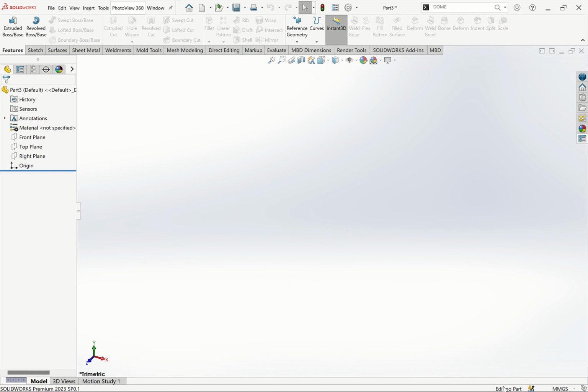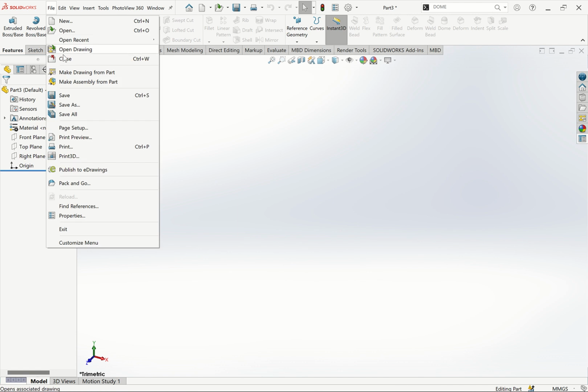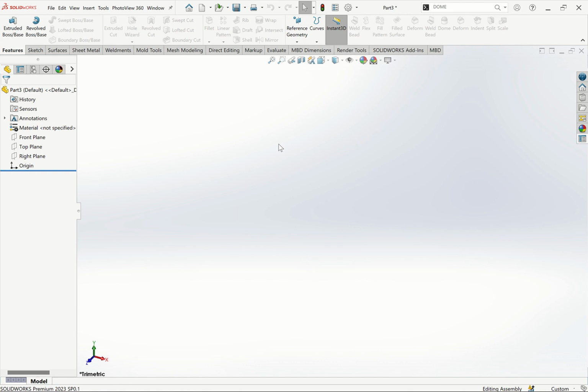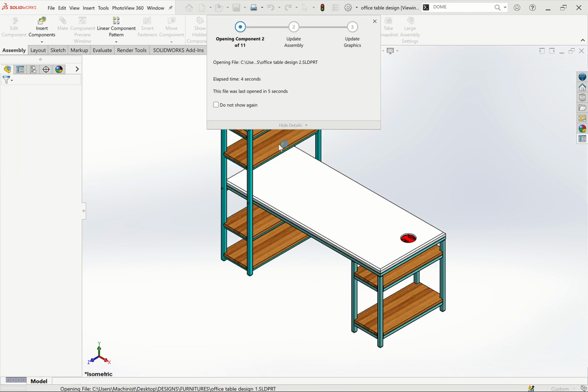In our status, we have three kinds of status: the fully defined status, under defined status, and over defined status, and then you have what you call editing. If the dimensions are not correct, it will always be showing here, and it also shows you the current app. For example, here it's telling me that my graphic performance is not good, so all the updates will come in here. For us to proceed, let me open a file of a design to explain the user commands, and then we'll go on to create a simple file to see how these commands work.